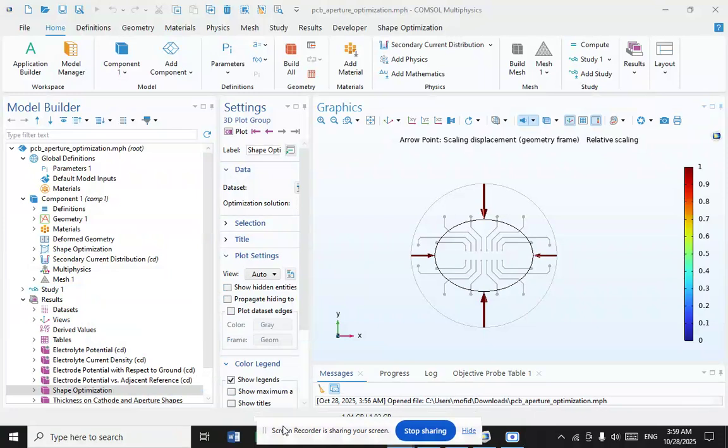Electroplating is the process of using electrodeposition to coat an object in a layer of metals. Engineers use controlled electrolysis to transfer the desired metal coating from an anode, a part containing the metal that will be used as a plating, to a cathode, the part to be plated. Aperture shape optimization is a method used in both radiation therapy and electroplating to determine the ideal shape of an aperture for a specific purpose, such as delivering a radiation dose to a tumor or plating a metal layer.